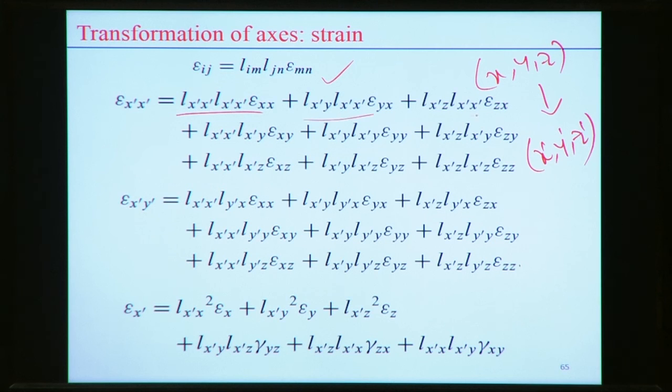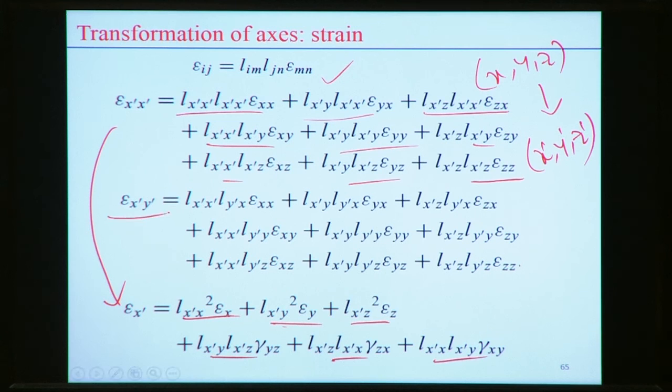Similarly, using the direction cosines, we can find the 9 components, and those 9 components can also be considered as 6 components given the symmetric nature of the strain components. Shear strain also can be calculated from the 9 components converted to the 6 components, similar to the stress analysis part.